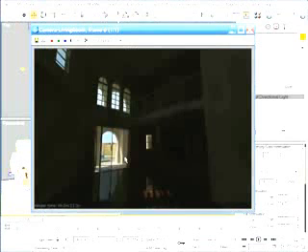If I hadn't switched to Reinhard color mapping and dropped the burn value to 0.5, I probably would have these outside surfaces illuminated just fine, but I know from experience that linear color mapping with the default settings is almost never going to work because there's always going to be burned out areas. And this is why I enabled a little bit of exponential color mapping from the start when I enabled a burn value of 0.5. So I don't want to touch the color mapping right now.